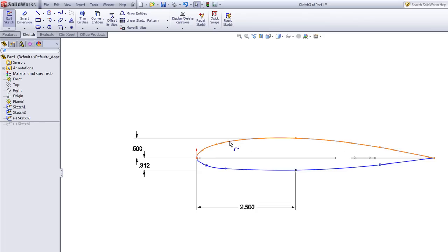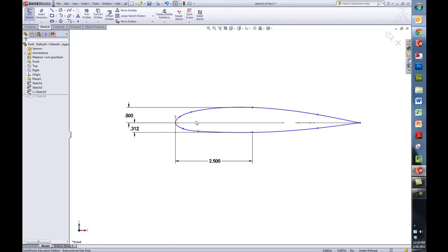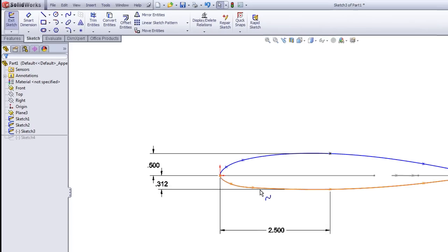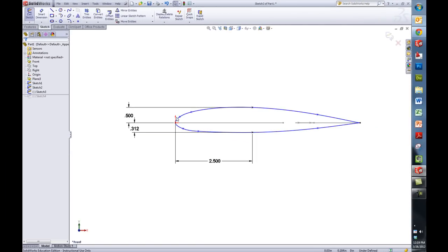And I'm guessing that this leading edge is probably real critical to the performance of the airfoil. So as your students proceed with looking at these, the better I can get a sense of this curvature, the more accurate I could produce it for them. So again, going to a tinier grid paper, 1/8 inch or even 1/16 of an inch, and having them give us a good profile here, and maybe with a much thinner pen rather than maybe a Sharpie or whatever was used, would make it easier for us to try and get fairly close to their design idea.